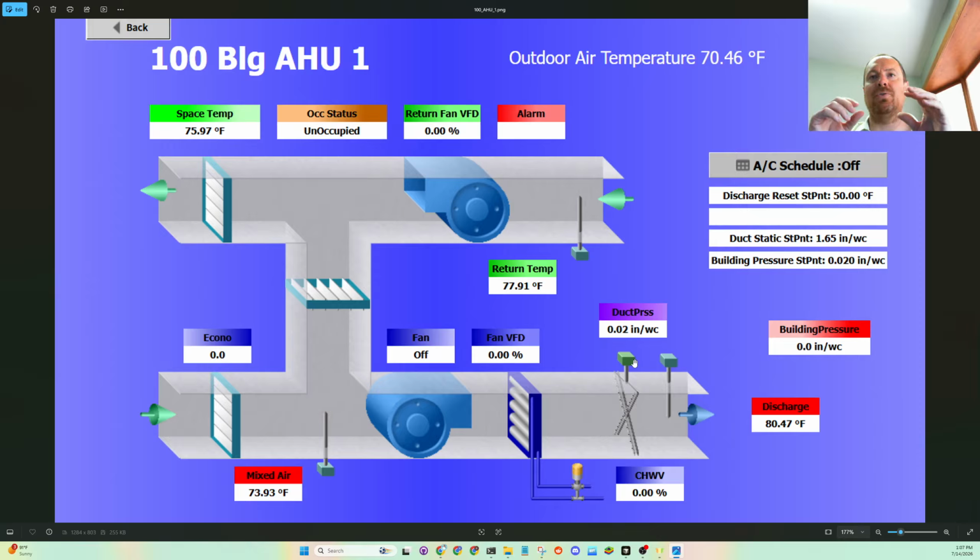It's like blowing up a balloon, where this fan operates like a kid blowing up a balloon. So it's pushing pressure up, trying to push the ductwork apart. So that's static pressure. Two thirds of the way down the ductwork is where the control sensor lives.